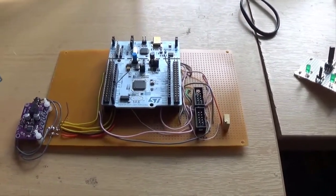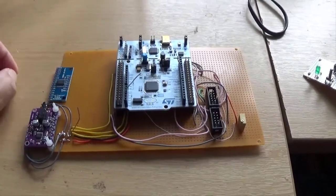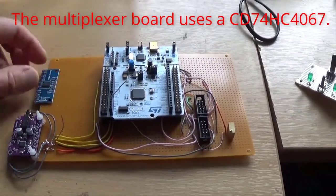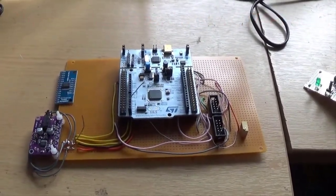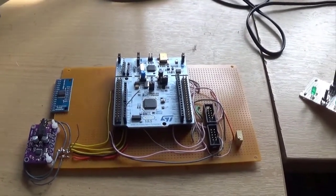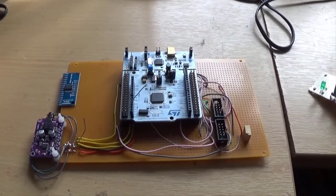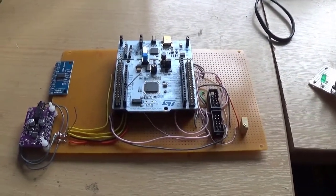So, to overcome this problem, I propose to use analogue multiplexer chips, which you can buy pre-stuck on a board. I've got one here and I'm going to try it first, and I'm not entirely sure that's going to work, but we're going to try it, which means not only do we have to process the analog input, we have to set the multiplexer up to look at the right pot and look at each pot in turn. That's why I'm doing that next. It's a bit more complicated.